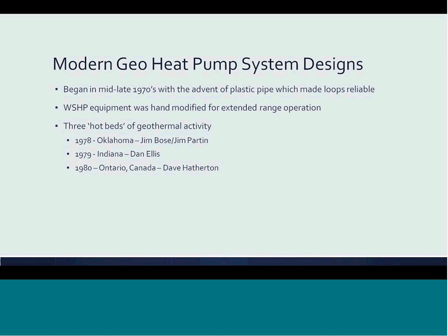So most manufacturers utilize both refrigerant low pressure and entering water temperature low temp protections or limit devices. Another difference is water and refrigerant lines could sweat within the heat pump cabinet and are insulated along with the entire coax heat exchanger, and that's all within the heat pump cabinet. Finally, all geoheat pumps now utilize thermal expansion valves, or TXVs.